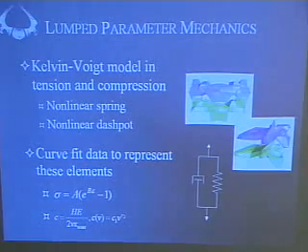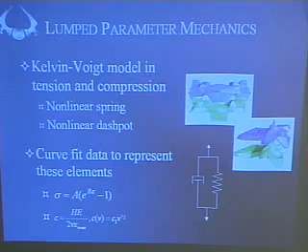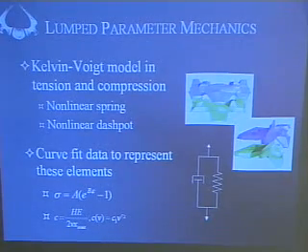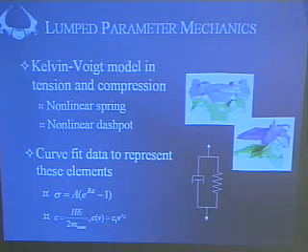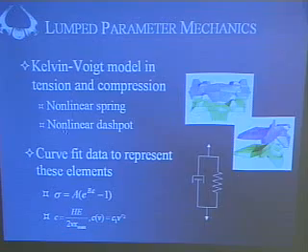And then for the dashpot coefficients, we calculated the hysteresis energy from a stress relaxation loading-unloading profile of constant rate. And from that hysteresis energy, we can calculate the exact coefficient for damping at a specific rate.